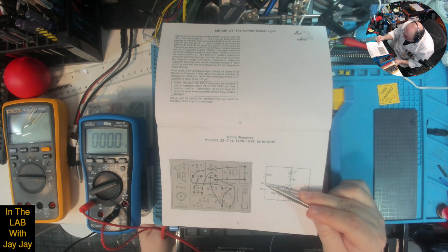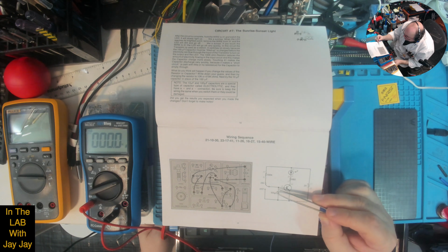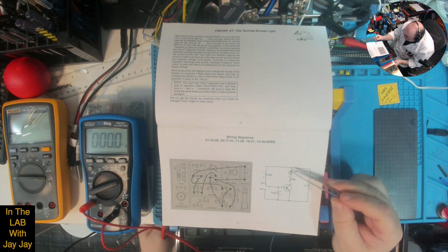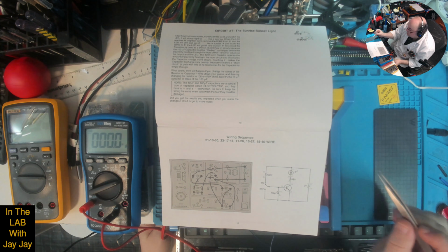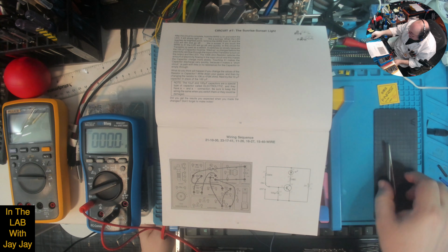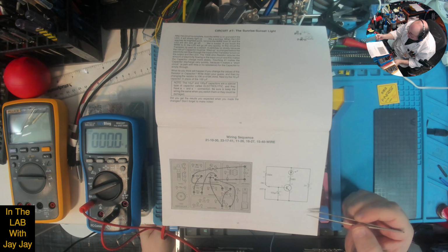And if you take the wire and you put it over here, that essentially shorts out the capacitor, which means it'll just drain pretty much instantaneously. And then there won't be any current on the base of the transistor anymore, so the LED will go off. So I hope that's clear, learning about how capacitors work and how they affect the base of an NPN transistor.